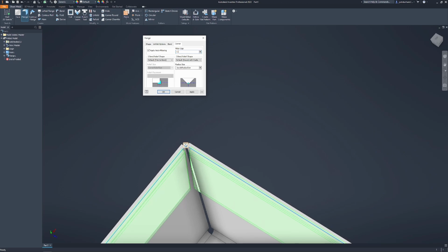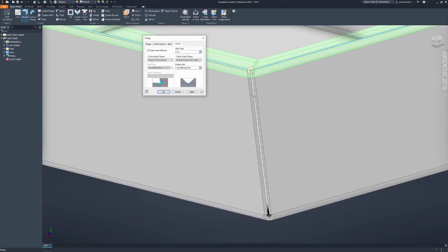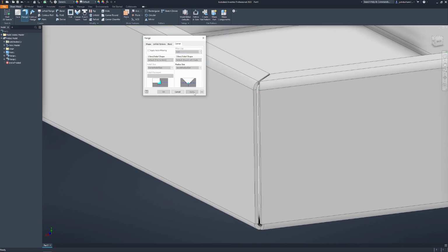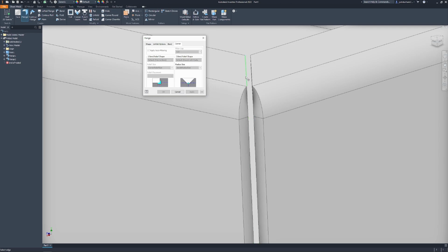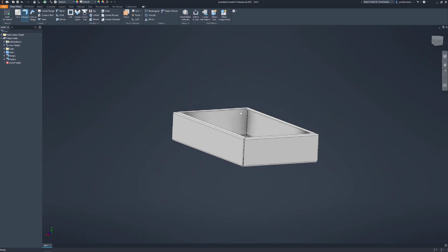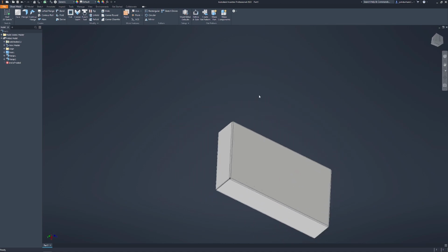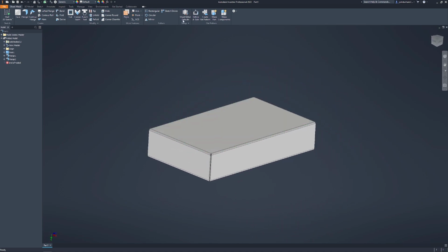And if we look at the gap size there, so that is that. And we'll go ahead and match that to this here, so it creates a consistent gap. Hit apply. Yeah, there we are. So if we're looking at that gap there and that gap there, that's both 0.5 millimeter. So on a 1.2 mil mild steel stock, that's absolutely fine. That's not a problem.